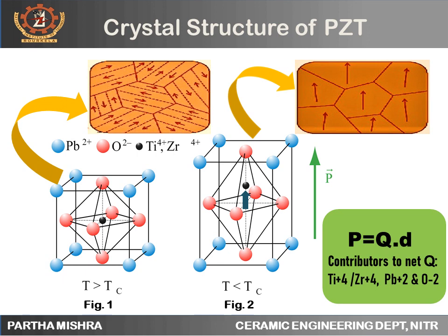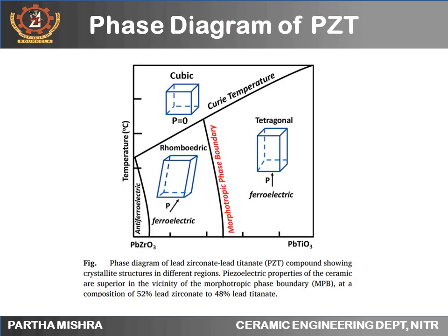This kind of coupling between the electrical and mechanical phenomena is one of the key causes of piezoelectric effects in such materials. As we saw, when we apply an electric field to a piezoelectric material, it causes the crystal structure to distort and its polarizability increases. So the dielectric constant and the piezoelectric coefficient go up.